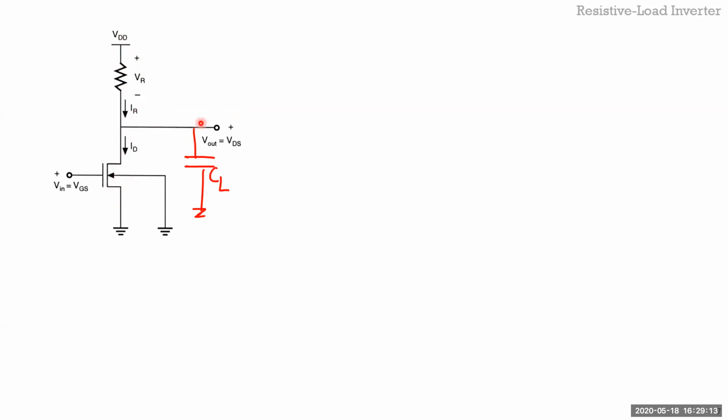So that's your output. When I switch this on, so I make this input VDD, this one turns really hard on, which means this resistance is very small compared to this resistance. So this will charge to a level which is a voltage divider ratio of these two resistors. That's your normal functionality.